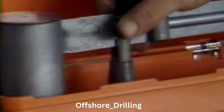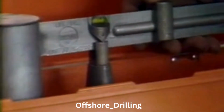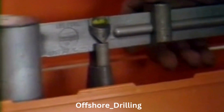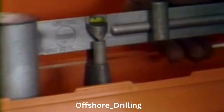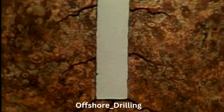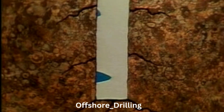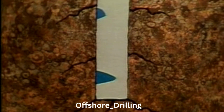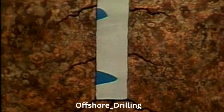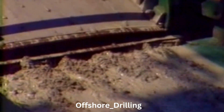Mud weight is usually taken every 15 to 30 minutes to help the driller and mud engineer determine whether or not the weight is remaining consistent. The intervals of checking might change according to the activities on the drill floor. Mud weight changes can be caused by salt water or freshwater flows into the mud, changing the solids to liquid ratio. Or it can be due to faulty cleaning equipment leaving too many drilled solids in the mud.